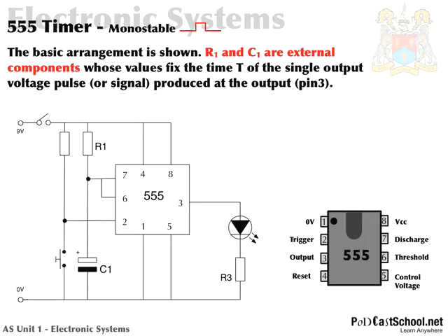And here is the basic configuration. So you can see now why we put 7 and 6 and 2 down this left hand side, because that's where we're connecting to, okay? And 3 over here, that was the reason for that odd layout. 4 and 8 are normally always connected to VCC, so they're better placed at the top. And of course 1 and 5 are at the bottom connected to ground, so that's why we put those there.